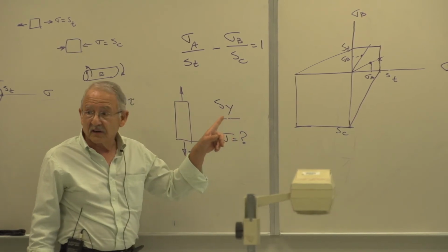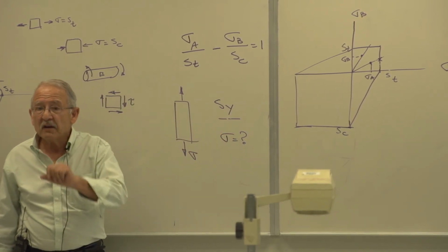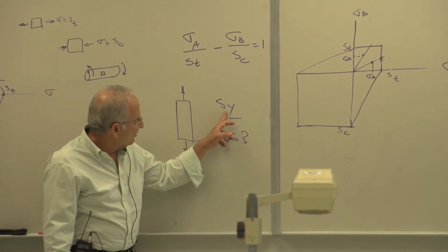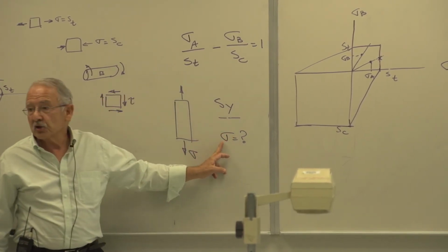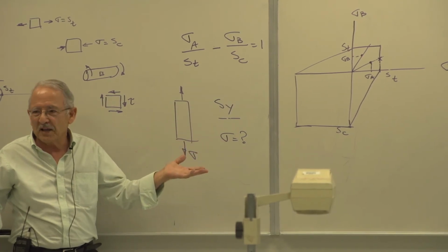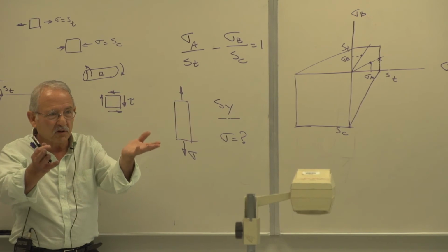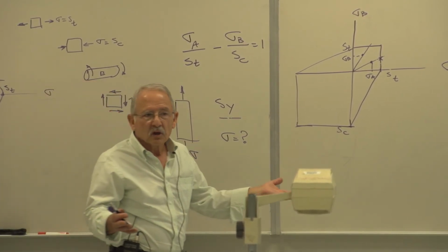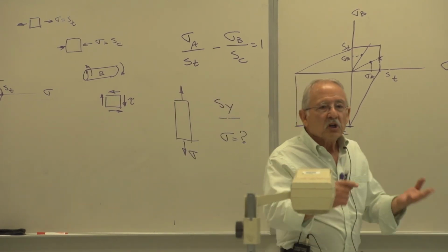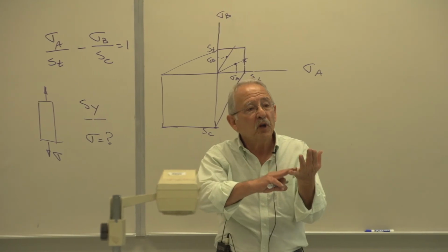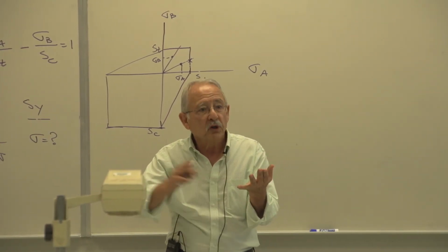Or you can say this. You can say, if you want to have a factor of safety of 2, with the strength of material like that, then multiply your stress by 2. And then solve for sigma. Of course, both of them will give you the same answer. Everybody follows that, right? So that's how we incorporate factors of safety. Either divide the strength by 2 or multiply the stress by 2 in this case.